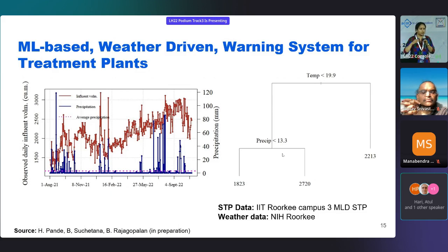And ideally, the design assumptions, even when we are designing these pipelines, are that if there is a rainfall event, the stormwater sewers will carry it. And if you have regular wastewater that's being generated out of homes, that will be carried through a different system. However, because of climate change, and because of these short spikes of rainfall, meaning very short durations of very intense rainfall that we've been experiencing again and again in various parts of the country, we are now witnessing a unique phenomenon, wherein the storm water is now making its way into the separate sewer system. So you must have seen this around you. Whenever there is water logging in a place, they will generally open the manholes, and they will allow the water to drain in through the manholes. But what are we doing there? We are accessing the regular sewer system that we have, and we are letting storm water into that. And this is not something that the system is designed for.